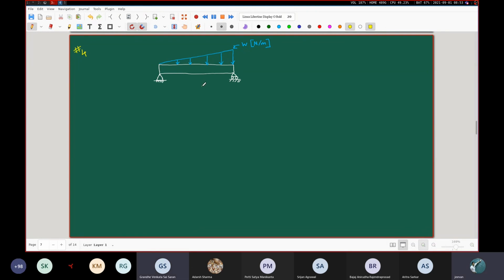So again, we find the equation corresponding to distribution of force. So here the question is again like before, that we have to find out the shear force and the bending moment diagrams. So we have to go from the left hand side to the right hand side of the beam. The only complication present here is that the distribution of load is triangular in nature. No other apparent difficulties here. So it seems like a straightforward thing to do.